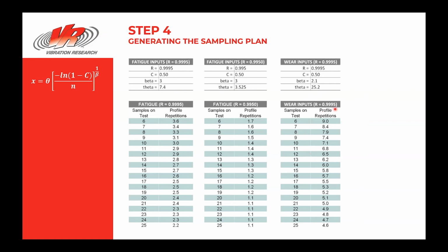So these are sampling plan examples, and it all comes down to really this Weibull success run formula that we derived here, and back calculating a characteristic life for a given reliability, strength distribution overlapping a customer usage distribution.